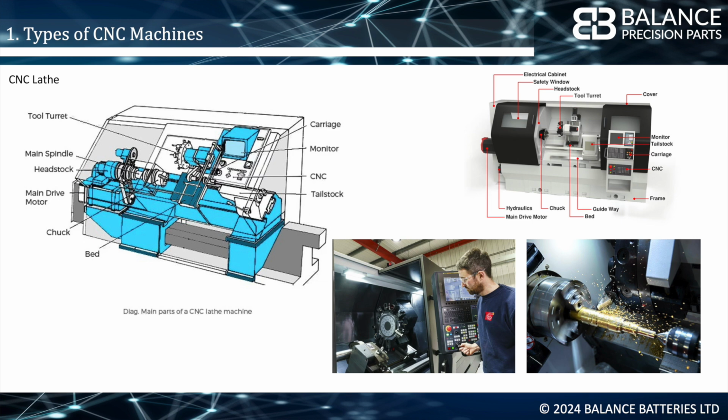The typical parts that can be made in this way are long cylindrical parts, as shown in the picture on the bottom right. Note that this is quite a long part and a tailstock is used to support the far end. It is possible to get a turret head with live tooling, which means motorised tools. In this way, the turret can hold a drill, which can then drill perpendicular holes in the end of the part, so long as they align with a plane running through the centre line of the part. In addition to live tooling, you can augment some stations in the turret with a 90-degree gearbox, which means that you can now drill holes perpendicular to the side of the part, but the centre line of the tool must pass through the centre line of the part.